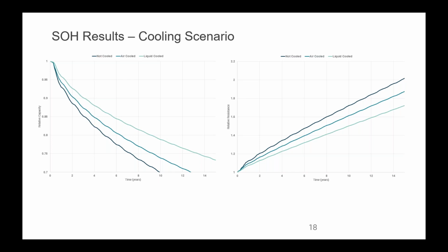So we see higher degradation in the summer, lower degradation in the winter, and that fluctuates throughout the lifetime of the battery, so that we're not using just an average temperature profile that we assume for the whole year, which you don't really know how accurate it is when you do that. So it requires multiple simulations to get an accurate aging prediction, and that's what we've done here.